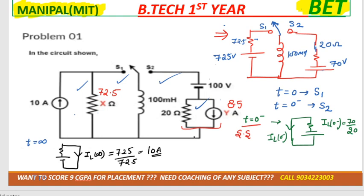Okay, so now at the transient condition, meaning t equal to 0, the switch is connected to S1, right? So the resistor is there and the inductor will behave as an open circuit, the voltage source will be removed. So in this case tau is equal to L divided by R equivalent. L is 100 millihenry, R equivalent we can get, that is 72.5 ohm. So we can get tau over here.